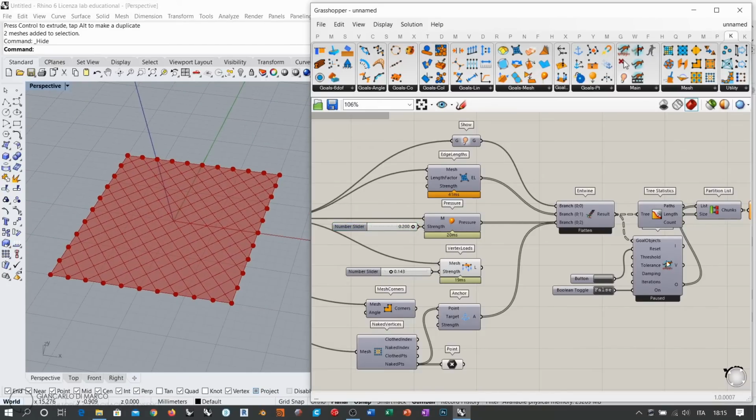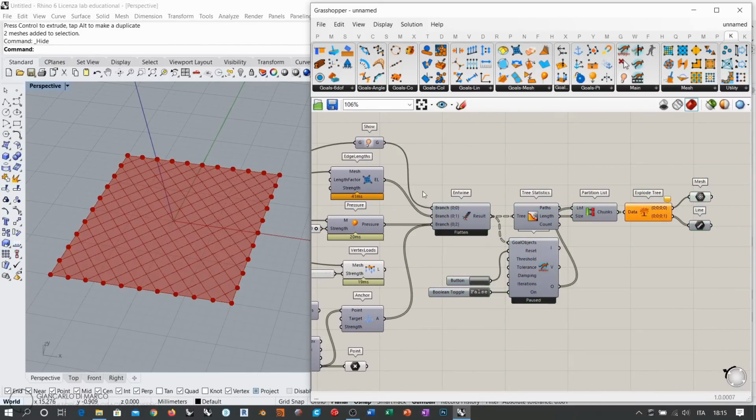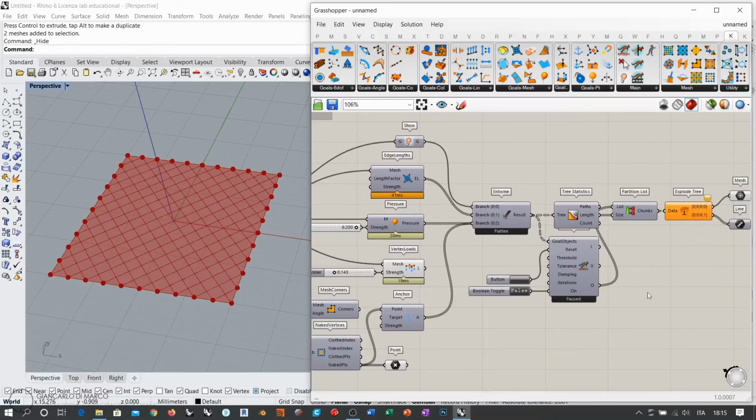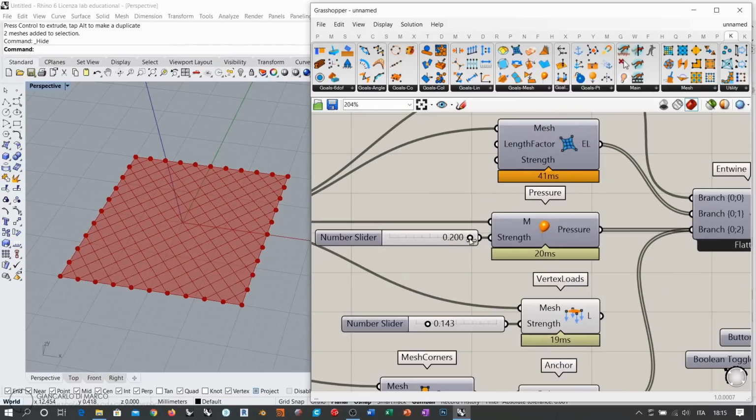So this is something that eventually has to do with the way the graphic card is affected by this thing here. But anyway, it's not a big deal. The system is still there, and the preview can be found in another viewport. The next time you open the same definition, it will work properly. So don't work with higher values for pressure. Always start with zero, and then eventually increase it, but very, very gently.